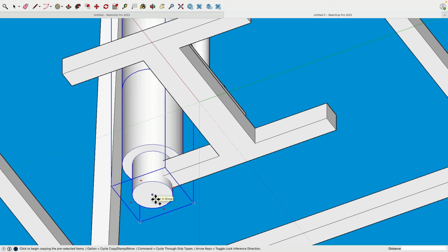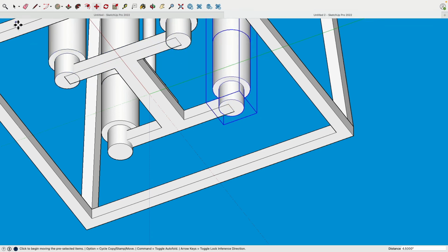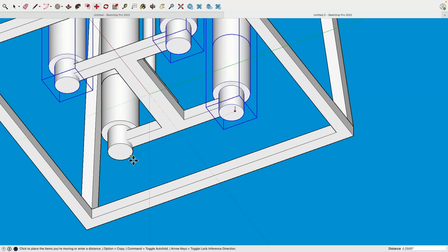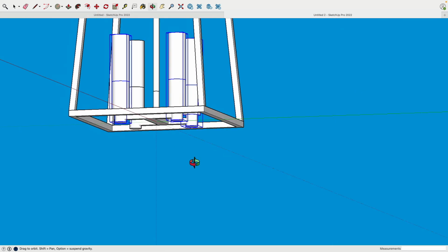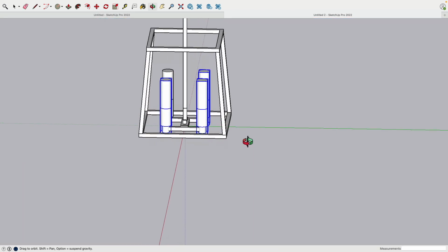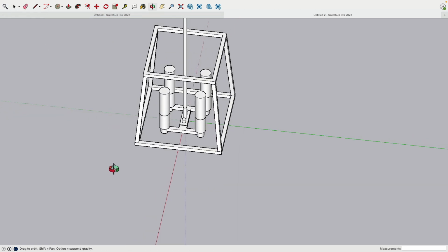you see how I'm selecting the midpoint, make a move copy to this midpoint. Now from there, that's easy, to there and there. And then I select all these 3 groups, go to the move command, move this along the z-axis till it snaps to this bottom point. Yeah, there we are. See? Super easy. The last thing now is missing.